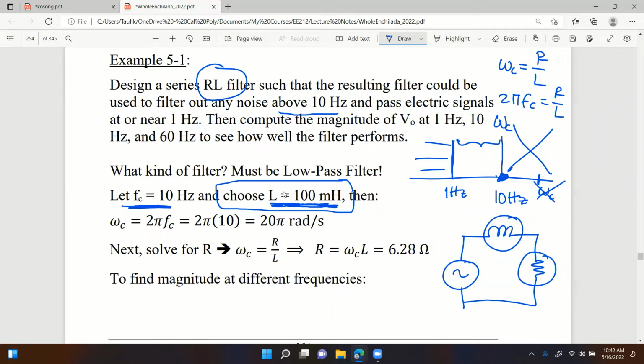The 100 millihenries, that's actually big, right? This is a big inductor. I don't remember why I picked 100 millihenries, but since I have a background in power engineering or power circuits, 100 millihenries is not uncommon. For power circuits, you usually use millihenry-type inductors.